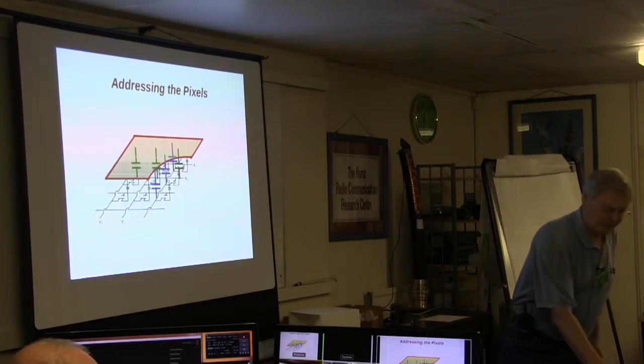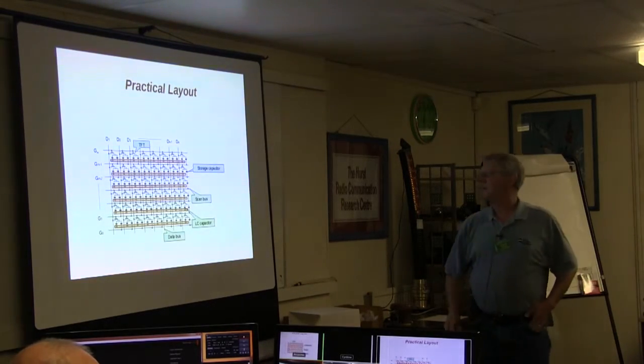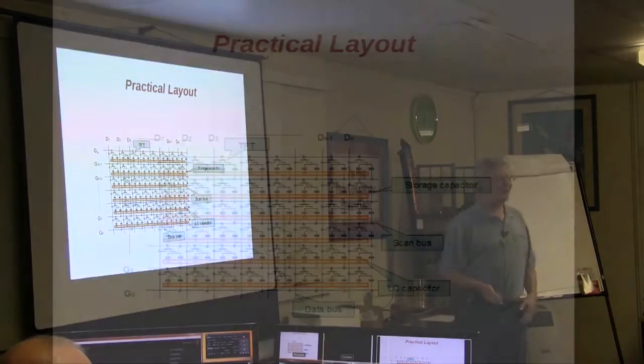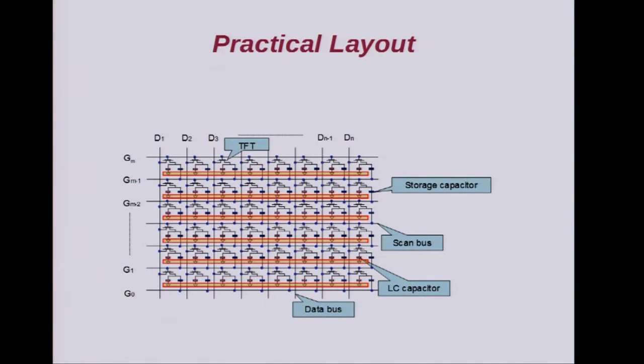It's not really enough, actually. This is a more detailed one which I won't hover over too long, but they typically add in, besides the liquid crystal, a real capacitor which is deposited on the glass with a metal film, and so it gets a little more complicated. Storage capacitor plus the liquid crystal, and then we've got the gate drive in the horizontals, and the drains are being driven by the verticals, the sources rather. This is data.